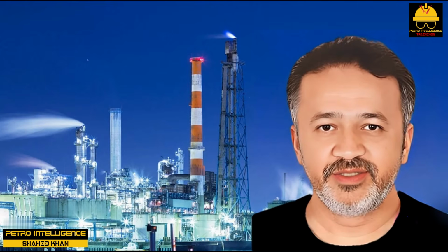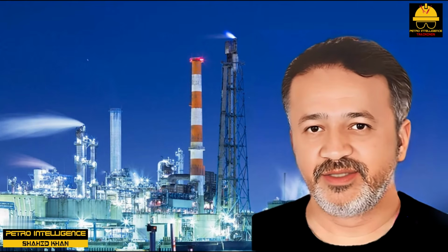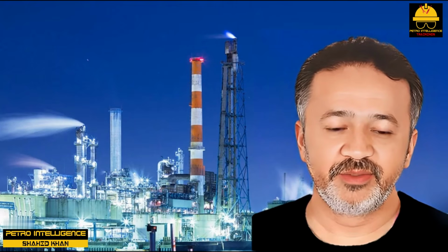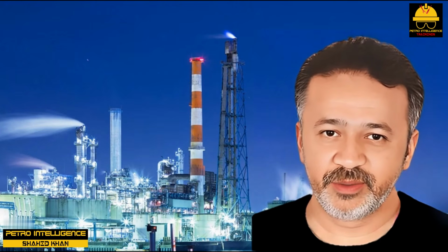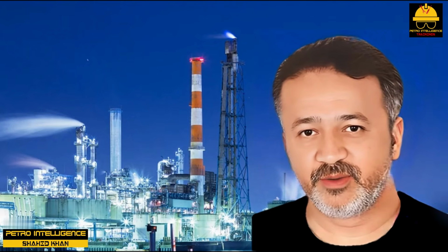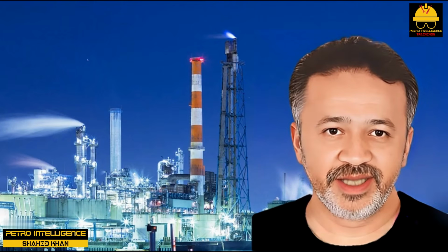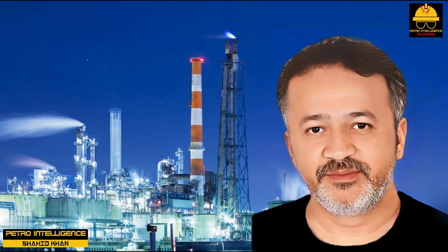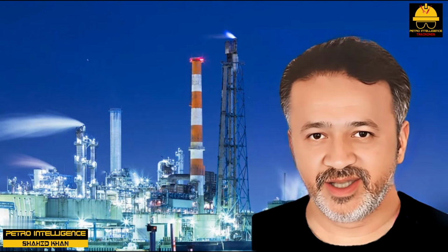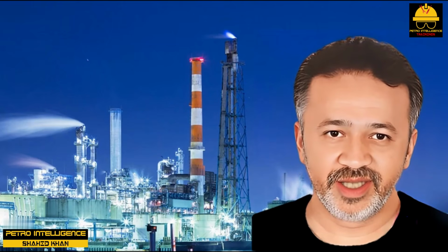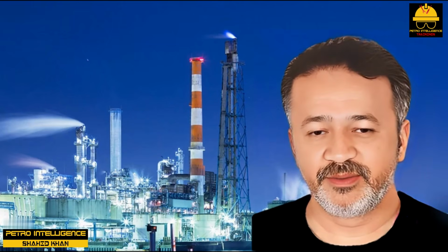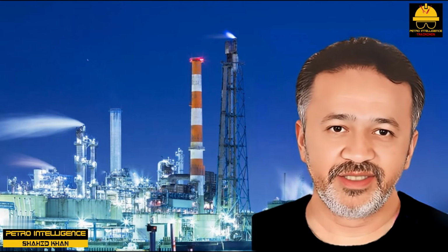Refrigerant composition. A very large percentage of refrigeration systems are not limited by the compressor driver horsepower, the condenser, or the evaporator. Many refrigeration systems are limited by either the compressor's suction volume limits, the mechanical pressure rating of the compressor case, or the refrigerant condenser shell.